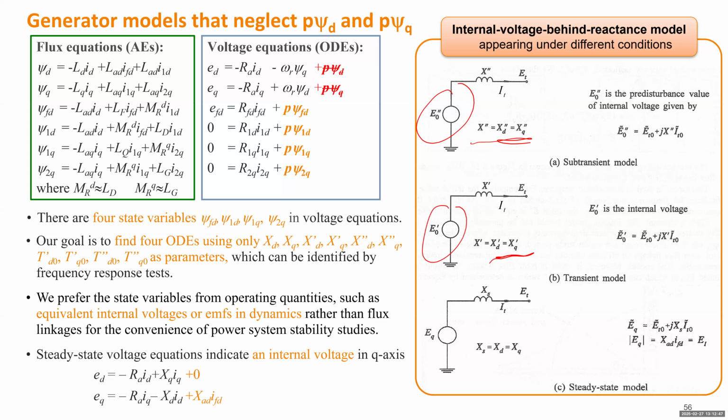So the transient dynamic has not started yet, and the system has not gone to the steady state. They have the same structure as the steady state model. They just connect the first model to the network and solve power flow. That will give you an estimation of the fault current.